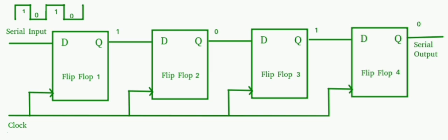ECL: basic gate OR/NOR, fan out 25, power dissipation 40 to 55 milliwatts, more power is dissipated. TPD 4 to 1 nanosecond, figure of merit 55 to 160 picojoules, noise margin 0.3. MOS: NAND or NOR, fan out 20, power dissipation 0.2 to 10, TPD 300 nanoseconds, figure of merit 60 picojoules, noise margin 1.5 volts.